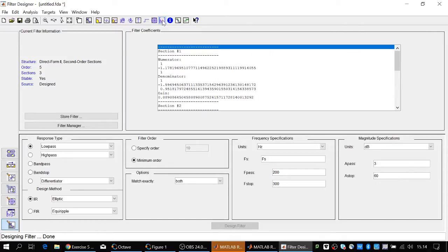Okay, how to use this filter design. Actually, a little bit about the structures, which is not today's topic. This is the so-called direct form with second-order sections. This design is based on cascaded second-order sections, meaning, well, you know what cascaded means, that we have those on the same line. So you have the first second-order system, then the second.